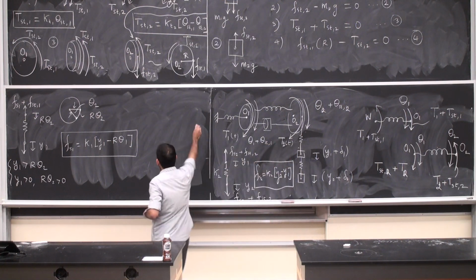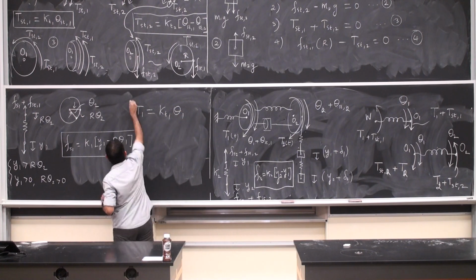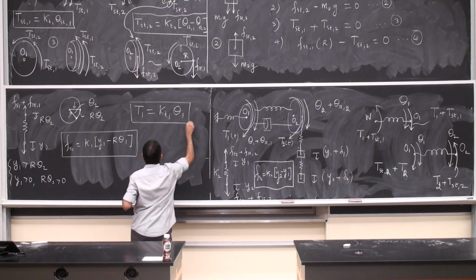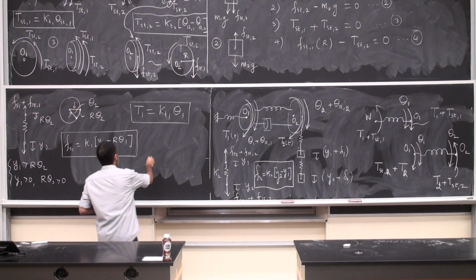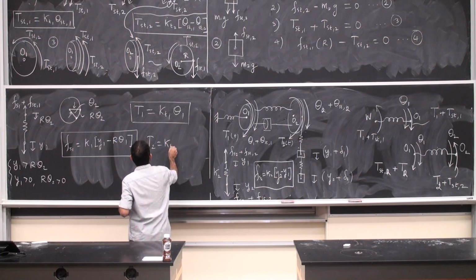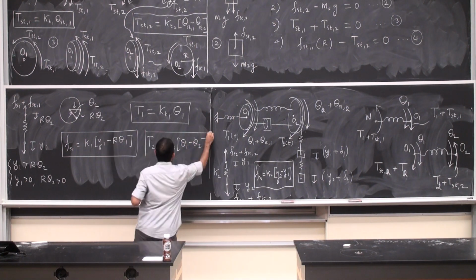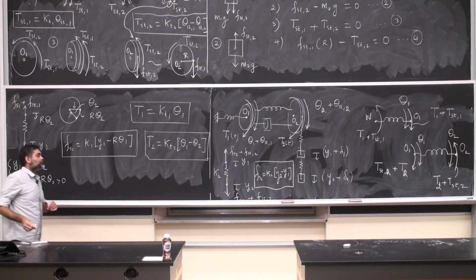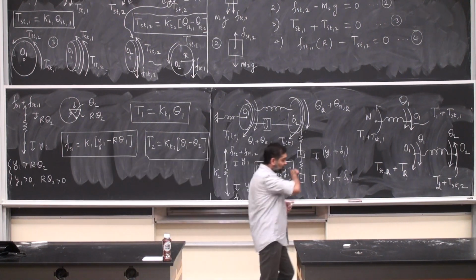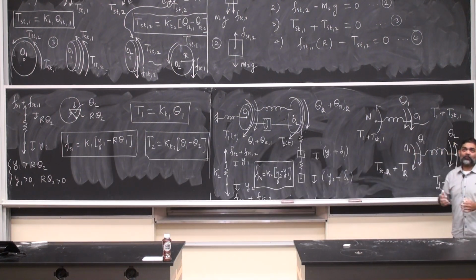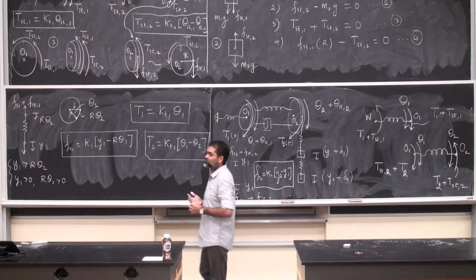So T1, okay, T1, theta 1, T2 written based on the way it is drawn here, theta 1 minus theta 2. All right, so that's all the force balances for the springs, and then we have to draw the masses themselves, draw the kinetic diagrams, sum moments up, and that's pretty much it. Okay, this is a cut and dry procedure for torsional elements.